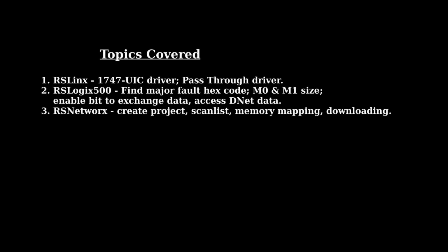Now, before you get any farther into this video, let's hit pause real quick and talk about what this video is going to walk you through. We're going to set up the driver in RSLinx for the 1747 UIC cable. We're also going to set up a pass-through driver, which is the only way to load the DeviceNet configuration into the DeviceNet scanner without physically being on the DeviceNet network.